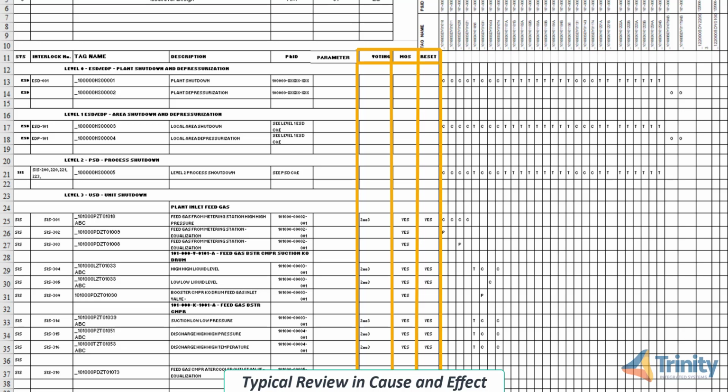Some inputs don't have latch. This is because they are feedbacks or valve position feedbacks. So whenever you see inputs being used for permissive actions, they don't have resets because permissives are not for tripping and we don't need a latch to hold them. Then review the IO list and categorize the tags, look for the typicals in the template project, and assign those typicals to the tags in the IO list.